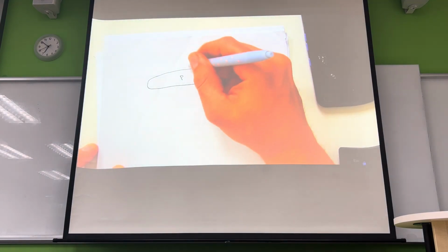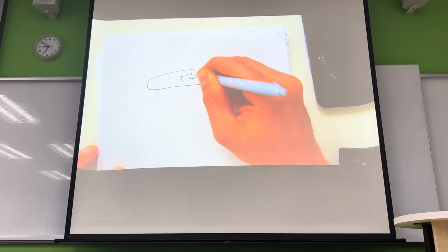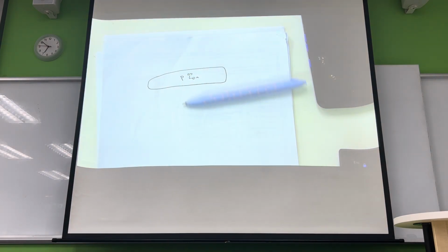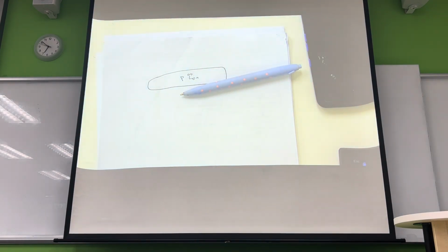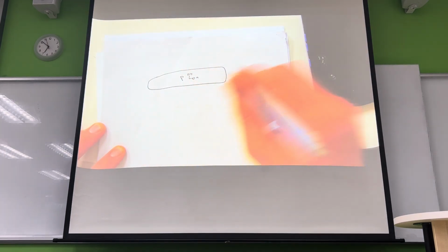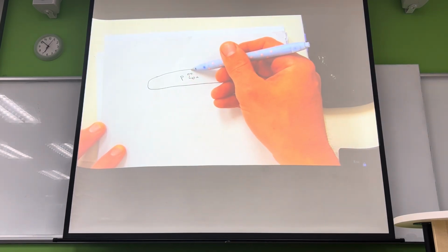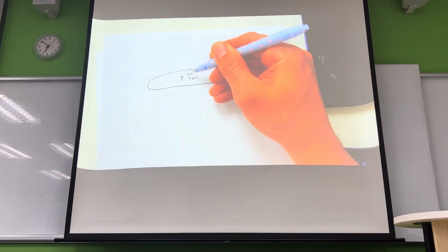If I say that I have X, Y, and obviously we know that X, Y, Z is coming out of the page. So Z is coming towards us. We know that this is going to be generating a stress in the X direction, the axial stress. It's also going to be generating a hoop stress, which at this point here is going to be going in the Z direction.